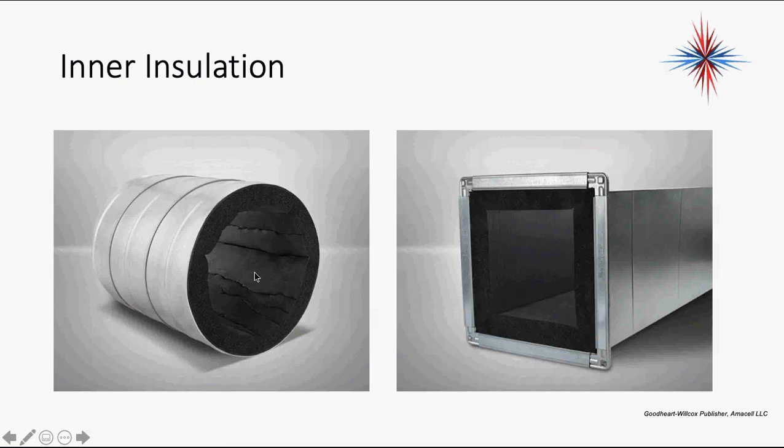So if you have a louder blower motor, or louder rooms, like in a commercial building, think about a school building. If we have a loud classroom and we don't want everybody else in the building to hear what's going on in that classroom, and we insulate the ductwork on the inside with foam insulation, we actually prevent that sound from traveling.